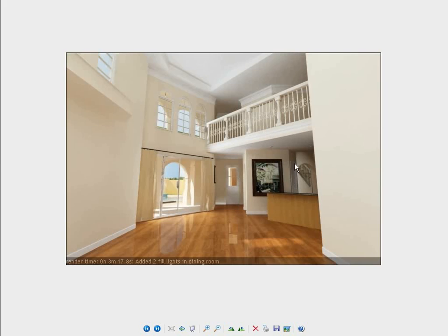So here's what the kitchen area looks like before the V-Ray light material is used, and here's what it looks like after it's used. There's a few changes to the specular highlights on the sliding door that is in the living room, and I see a tiny change to the actual light fixture itself, but there's no discernible change to the illumination in the kitchen. And that's not a big surprise to me because the size of the light cover is so small. The size of the surface area emanating light is so small.